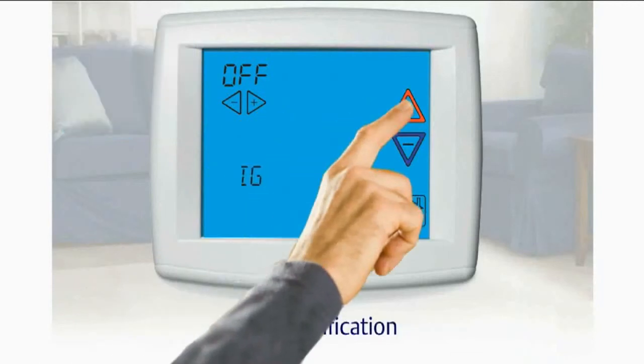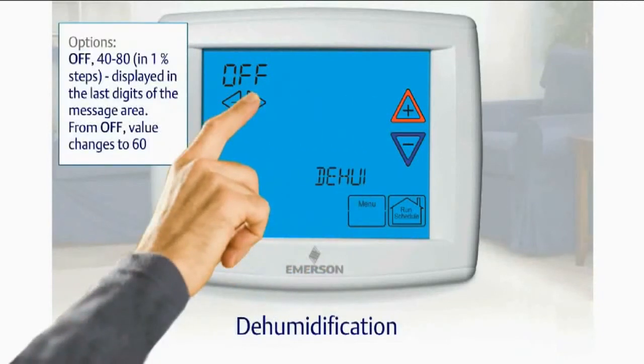Menu item 11, dehumidification. You have a choice of between 40 and 80% relative humidity settings for the dehumidification. If the relative humidity is above the setting, a cooling call is initiated. To turn this feature off, raise the setting to its highest level of 80%.